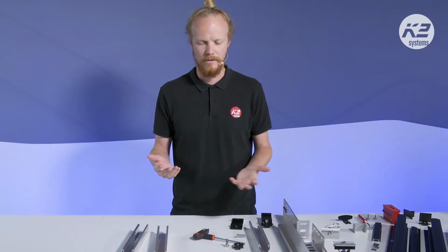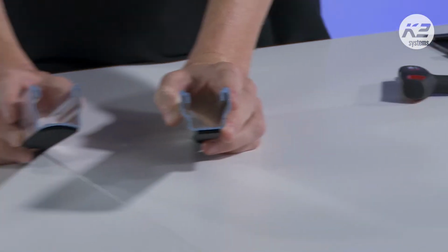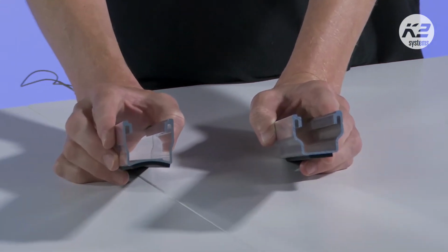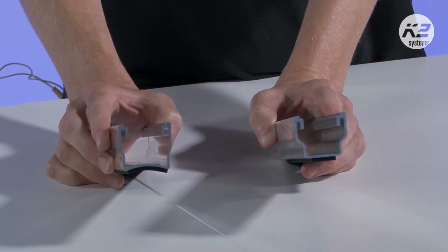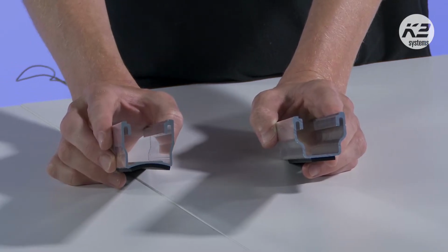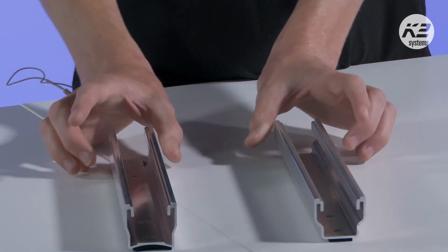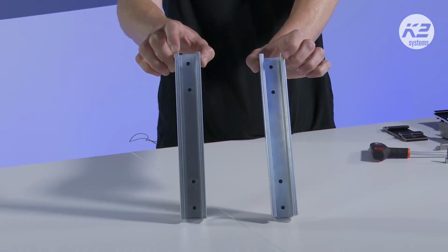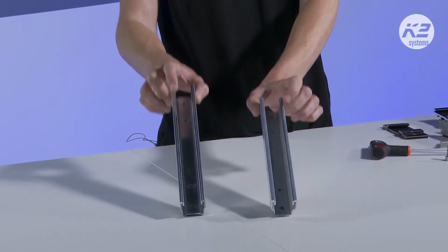So the easiest one to imagine is the MultiRail system that we have with clamps. The MultiRail with facade clamps is very similar to our MultiRail for trapezoidal roofing, just with a few additions. And so using our MultiRail or our MultiRail CSM, this is for rounded or waved corrugation roofing. Just be aware of the direction of the corrugation in this one. This needs a vertical corrugation. Both of these rails will sit on the facade like this. So if your corrugation is horizontal, then it's not going to work with this solution. Just be aware of that.